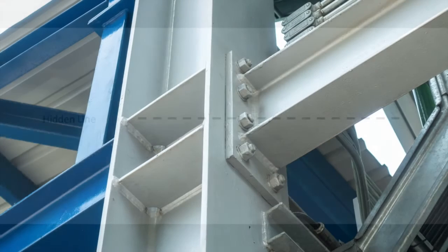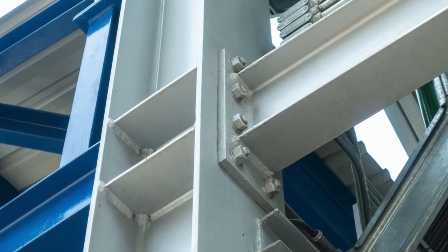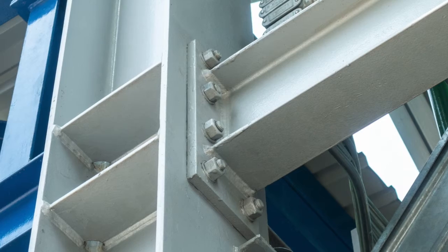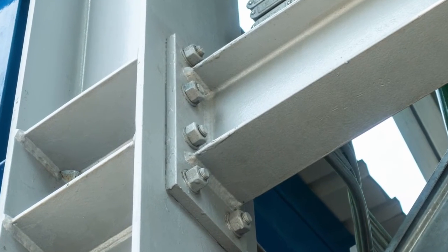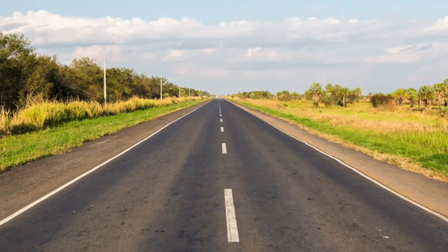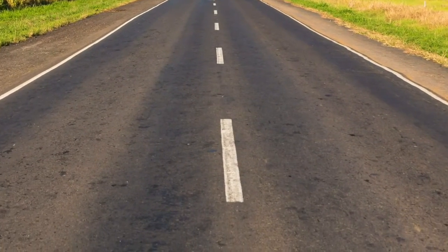A hidden line is a medium-sized line that is broken up with even-spaced dashes. It is used to show concealed edges within a part. For example, you may not be able to see a support beam from a front view. In order to represent that the support beam is physically there, but you cannot see it, an engineer will use a hidden line to represent the beam. Think of a hidden line as a dashed line in the center of a road.